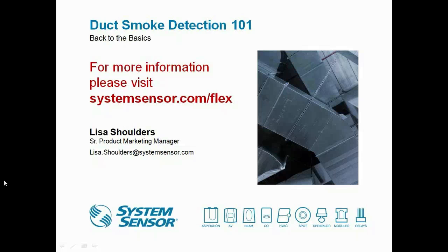The main importance there is to ensure that the exhaust tube that is shipped with the product, in the parts bag there's a small exhaust tube, is long enough to protrude into the ductwork. If it is not long enough, we do sell a longer version of our exhaust tube that can be purchased separately when it is needed.